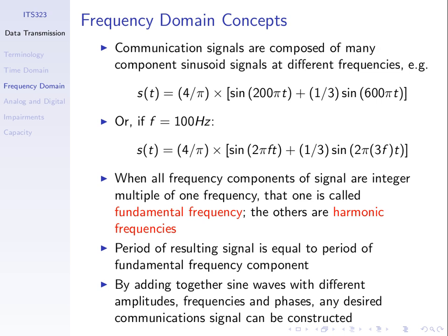And we can find the frequency. Frequency 1 is from yesterday. The frequency of component 1, anyone? Was 100 hertz, because general equation 2 pi ft, we have 200 pi t, f must be 100. And of component 2, we got 300 hertz. And the signal on the screen is just a summation of those two.